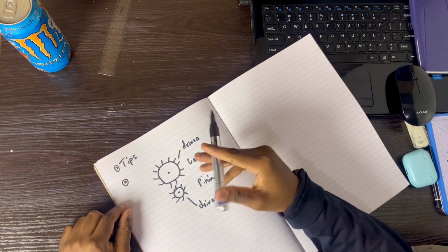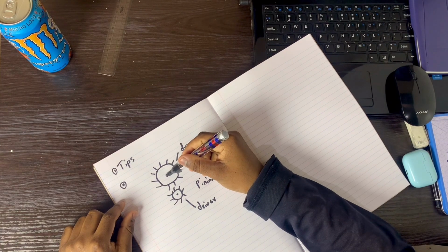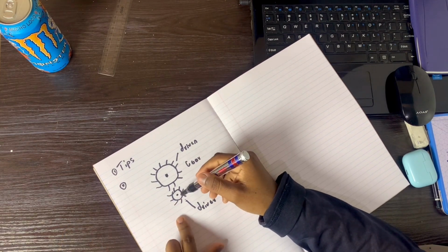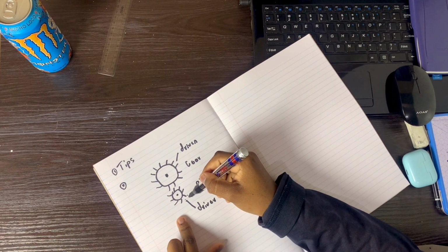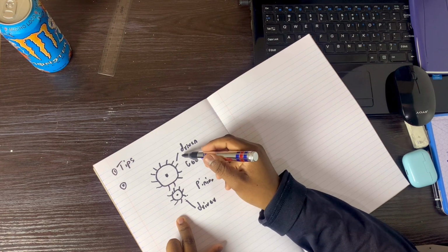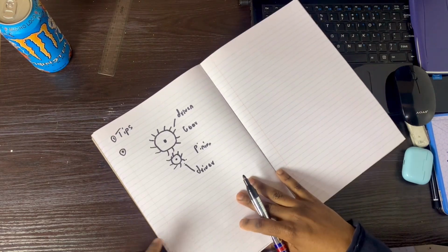So one thing you have to be careful of: most of the time it is given that this gear is the only one that is connected to the shaft. So the torque that is being produced by the pinion is not going to be the same as the torque that is going to be on the gear. That means the torque on the shaft is not going to be the same torque that is produced by the pinion. But you get to see that once you attempt the tutorials.